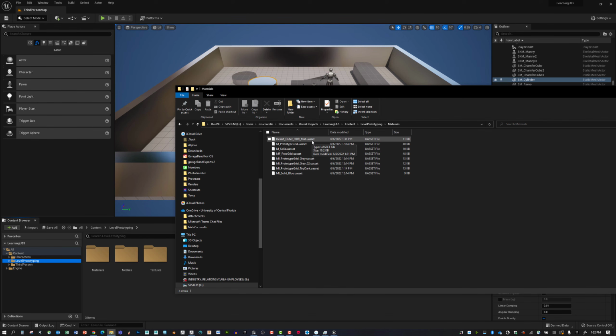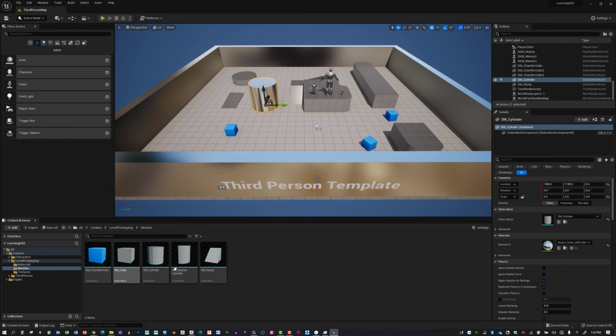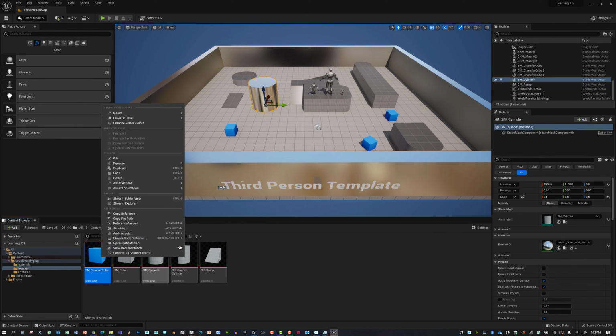Take a note on here that this is a .uasset, so that's an Unreal asset, and that's their own proprietary format. We will look at this a bit more, but if you wanted to get these models out, it is possible to select this, right click on it, and then choose asset actions, and you can export that. We could export that as an FBX, and that's one way to get that out of the program, and we could import that into a program like Maya.